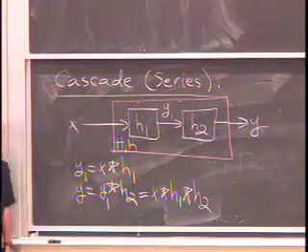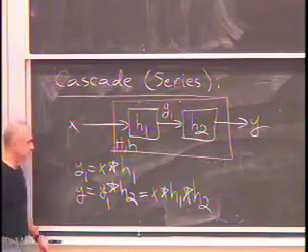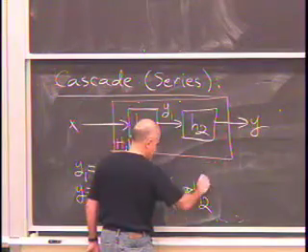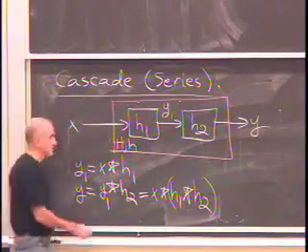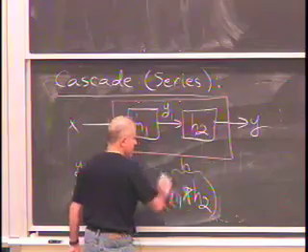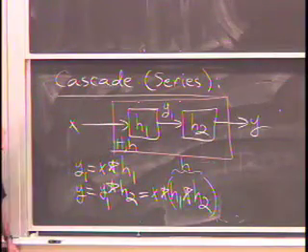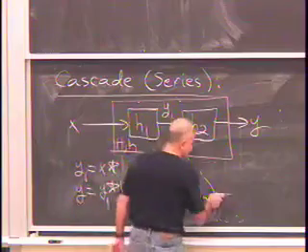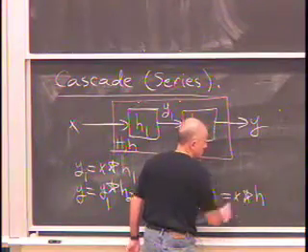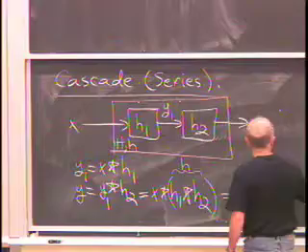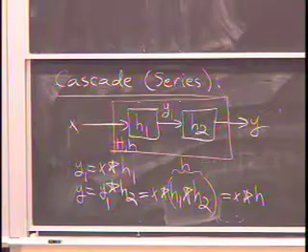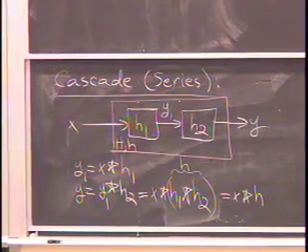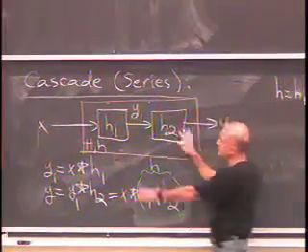And there's this nice little property that if you've been doing the reading, you would have seen by now. It's the associative property of convolution. You take two of those three and bunch them together, and this must be H. So it's X star H, which means the impulse response of the overall system is the convolution of the individual impulse responses. Does it matter which system comes before which one?